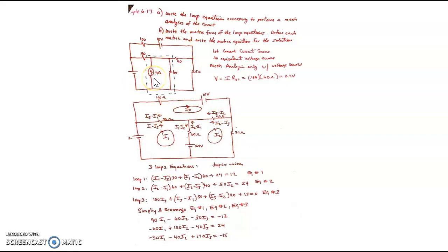But the first thing to do is, okay, I have two voltage sources and I have 1 current source. So the rule is that they all have to be voltage sources. So I have to transform this current source into a voltage source. In order for me to do that, I have to find a resistor that is directly parallel to this source. So the 30 is not parallel because it is connected here. But in order for it to be parallel, this other terminal has to be connected to this end of the source. So this is not parallel.